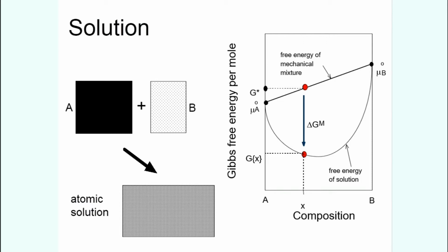The same thing in solid state is also a solid solution. There is no difference at all. You have to put one into the other. Here you have A and B. A is bigger, B is smaller. You are adding B into A, so that B gets dissolved into A, just like salt gets dissolved into water. Water content was bigger, salt was very small, one teaspoonful, right? Same thing, you are putting a small amount of B into a large quantity of A, then there is a solution of B in A. It can be vice versa, like you have a large quantity of B, then you add a small quantity of A.